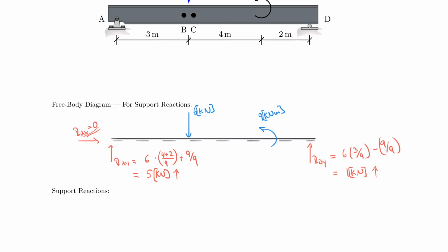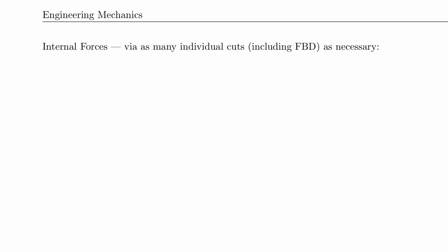On this page, I will now go ahead and draw the internal force diagrams for any location I need to find the values. So look at the headline here, and please understand that you have to calculate your internal forces via as many individual cuts as necessary.